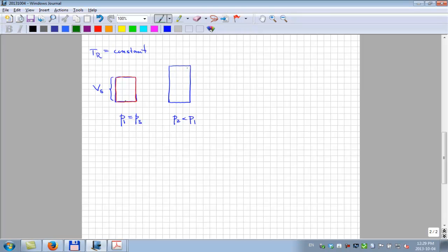So then we go to here, and now, since we're at lower pressure, we condense out through retrograde condensation some liquid, and that forms at the bottom of the cell. And the rest of this is, of course, gas. It's a different gas.